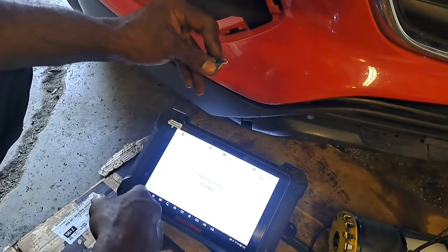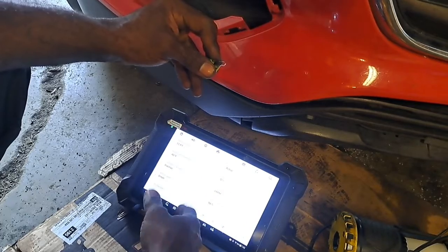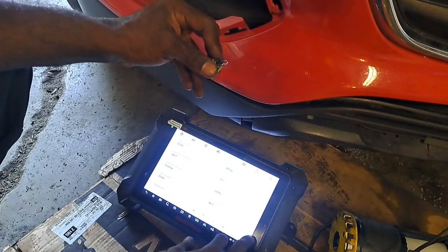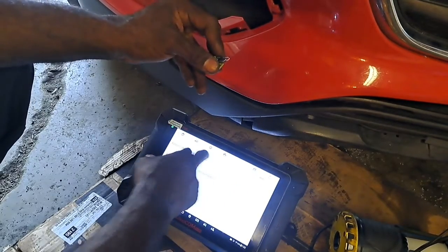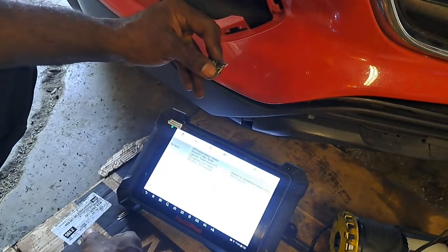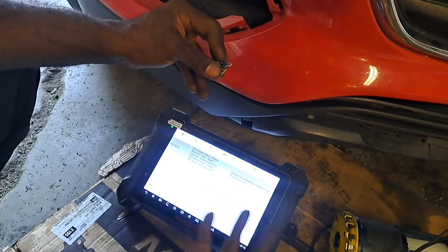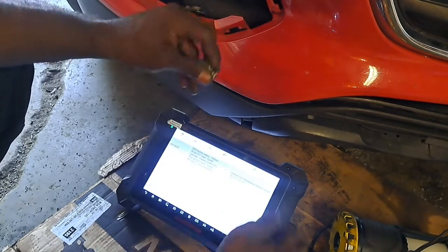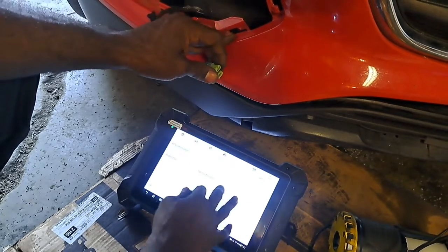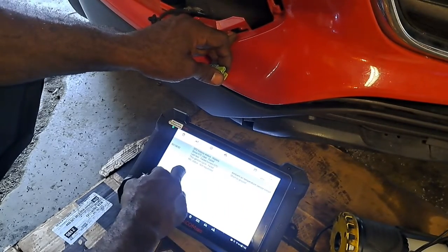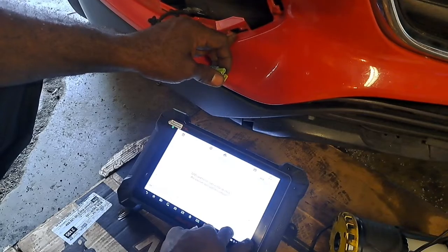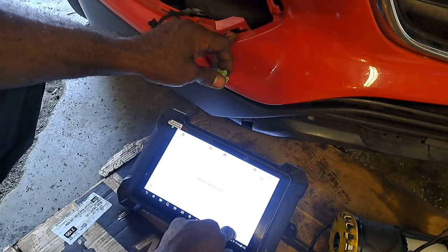Let's go to live data. Should be maxed out. Nope, it's still at negative 40. It's probably got like a short code now. Let me see what comes up. You know, it's still short to ground. Let me take that off. It was 158. So we had a B0158. Let me see if it changes. 158. I can't remember the last code.